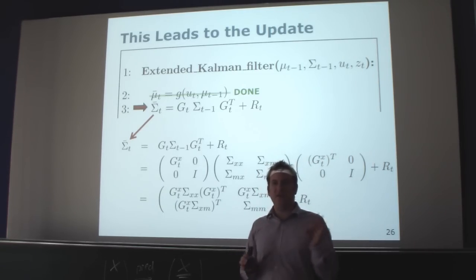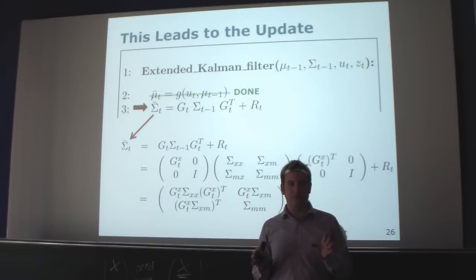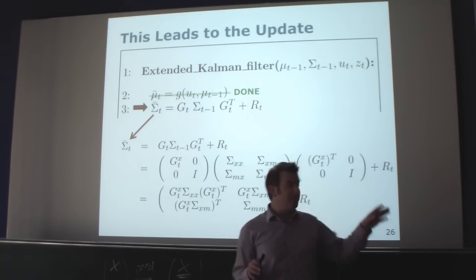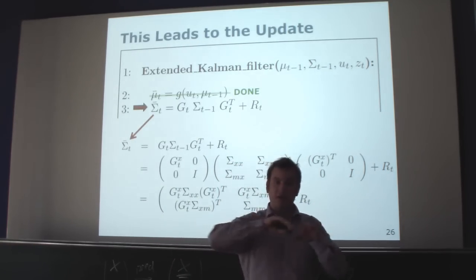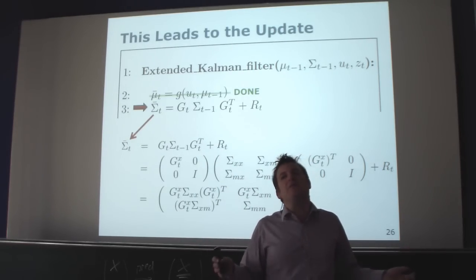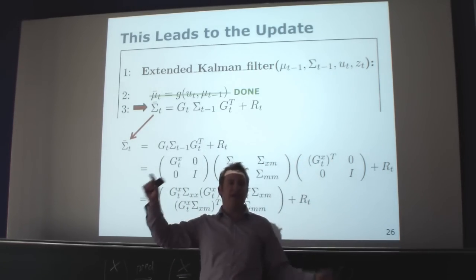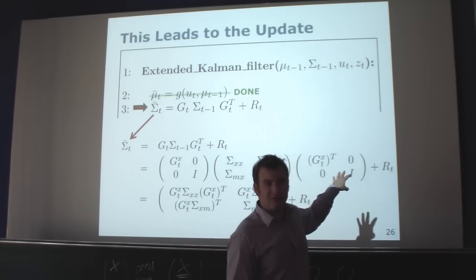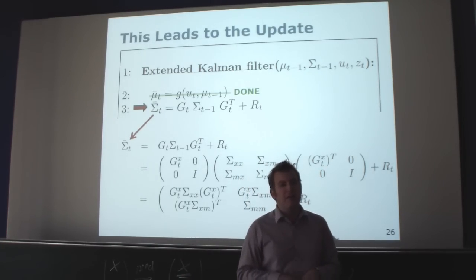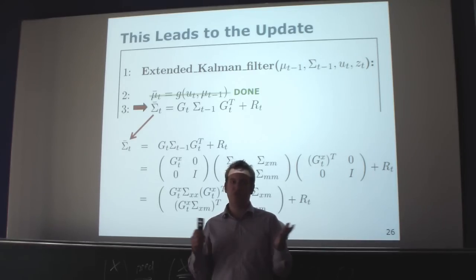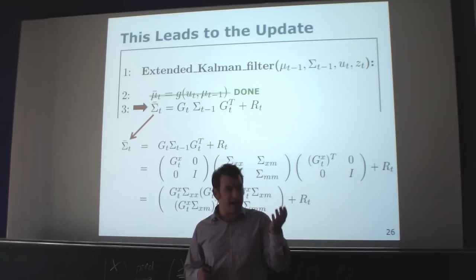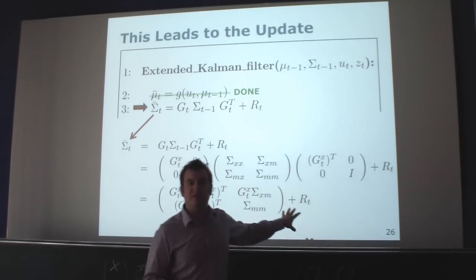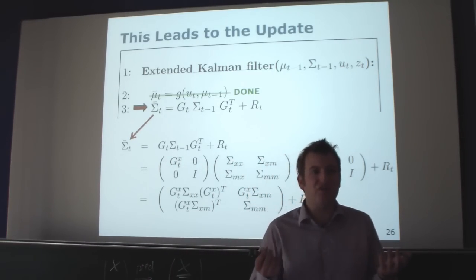In the EKF, we have the issue that everything has to be a Gaussian distribution. It's the assumption we have in there. Therefore, this term gives me a regular covariance matrix, not because the Gaussian is not able to take into account the banana shape. The model is clearly imperfect. It's not perfect. I just have linearized my nonlinear function to propagate my belief through that linearized function, which is definitely not exactly what happens in the real world. So it's clearly the case, you're right, this doesn't give me a banana-shaped distribution. The reason for this is the EKF can't handle it. It has to be a Gaussian again.